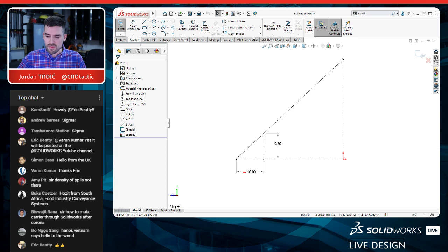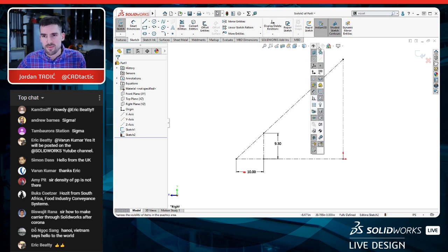Let me show you this too. Something I always like to do whenever I'm getting into creating equations or linked values, on the drop-down menu, that kind of creepy looking eyeball in our interface, there is a D1 option. So that shows the dimension names. So go ahead and activate that.